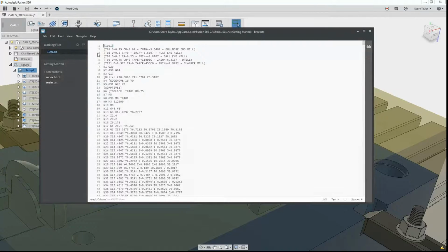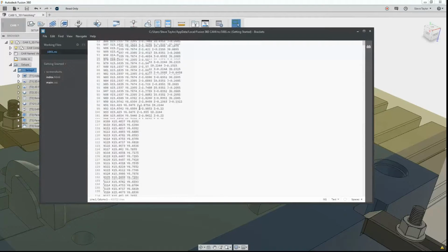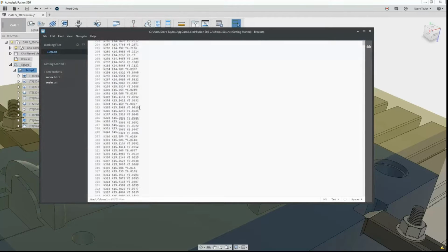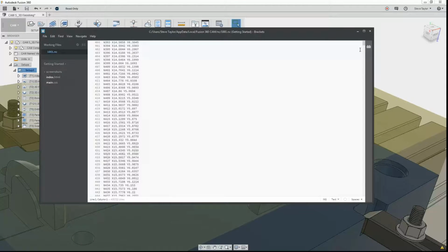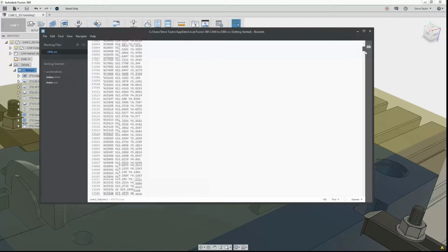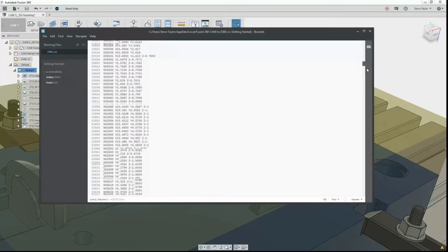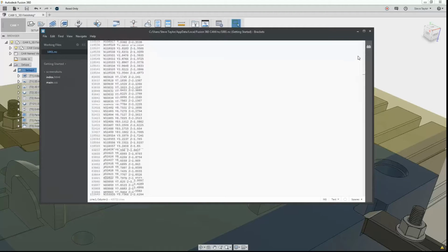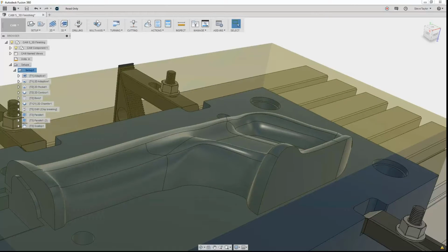And there we go. This is all our machine coding, all our encodes, all our coordinates, all our Gs, tool changes, everything's in there along with the tooling list. So all the G codes are there, all the information on the tooling changes, you can program in manual stops, you can build it in. Everything you would expect from a mature CAM program has been built into Fusion 360.